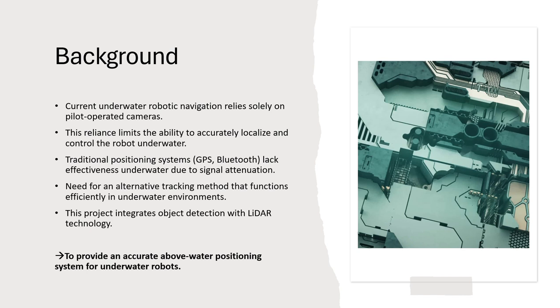So this project evaluates object detection with RPLiDAR technology to provide an accurate above-water positioning system for the underwater robot. It means that our positioning is based above the water, which can cross-track with the underwater positioning checking.